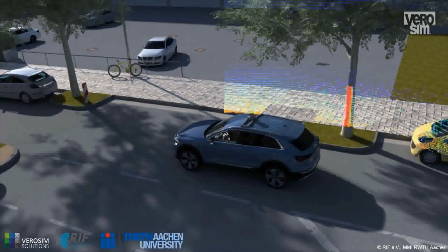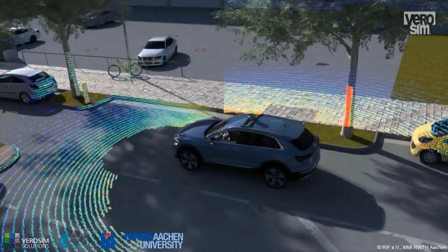We are not only simulating camera sensors, but also lidar sensors, which are really important for highly automated driving as well. And here we are not focusing on single manufacturers, but we want to provide a very generic as well as physical sensor simulation, which can be parameterized and configured to mimic a wide variety of sensors, sensor types, for example camera and lidar, as well as sensor versions, for example a multi-layer lidar sensor, as well as flash lidar sensors from different manufacturers.